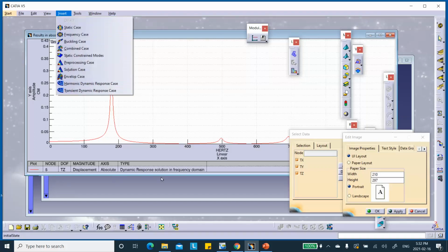In the next video, I'm going to redo this problem, except that the amplitude of the force depends on the frequency. In this case, it was constant, the 40 Newton that I applied. But it can vary. For example, in the centrifugal force of an unbalanced rotating machine, the magnitude of that force is m r omega squared. It's not a constant; it's a parabolic function of omega.